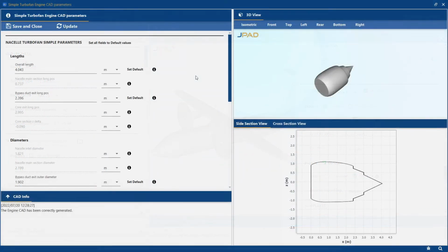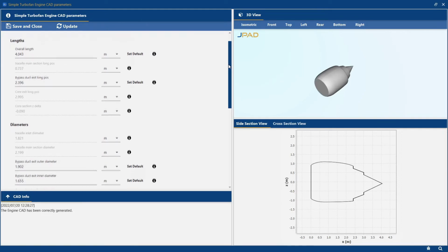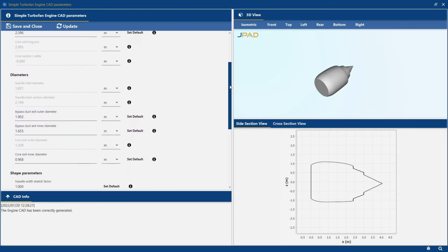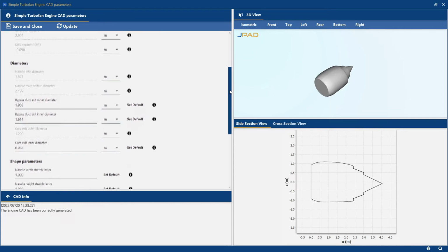The turbofan simple nacelle load is the simplest primitive for turbofan engines. Like the previous one, this load mainly relies on the set of input parameters for the engine geometry already specified in the Input Manager at the Nacelles and Powerplant tab. These are reported in the Turbofan Simple Details window, as uneditable fields in the left scroll-down menu.